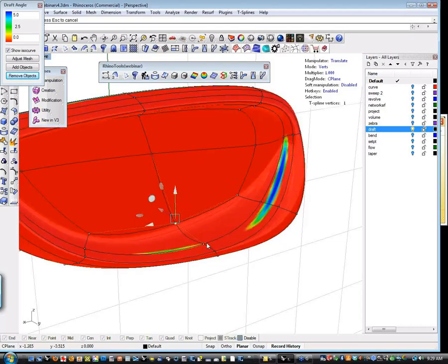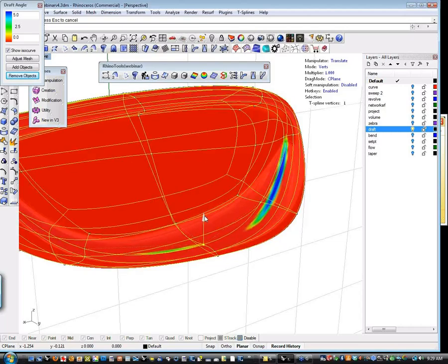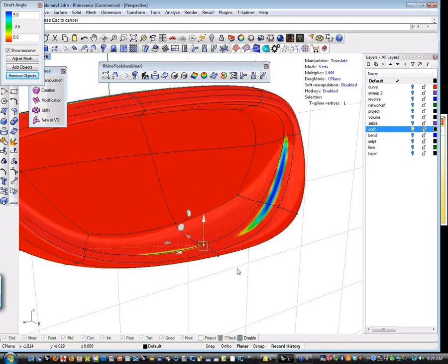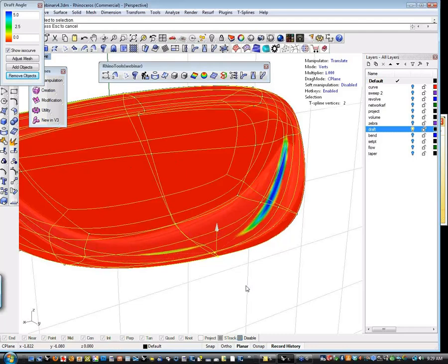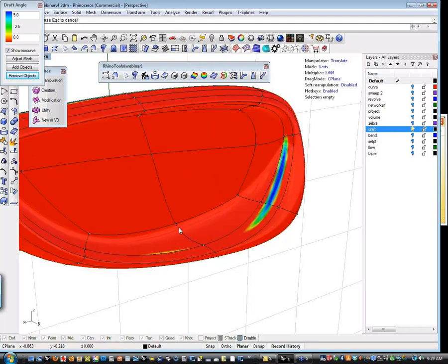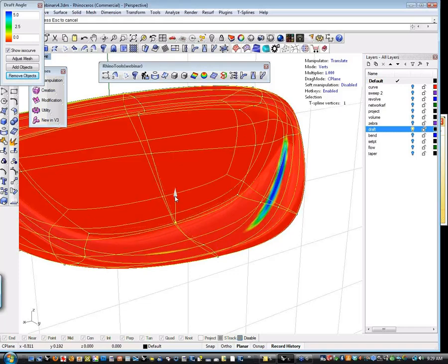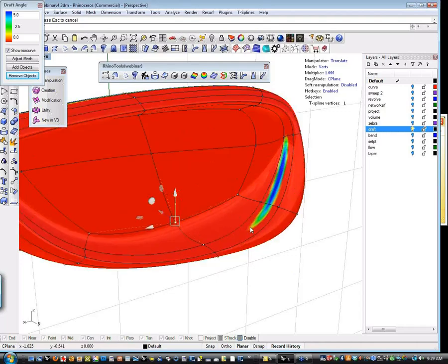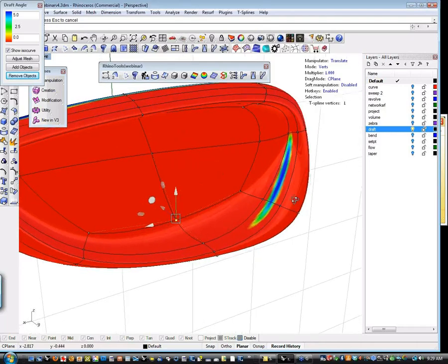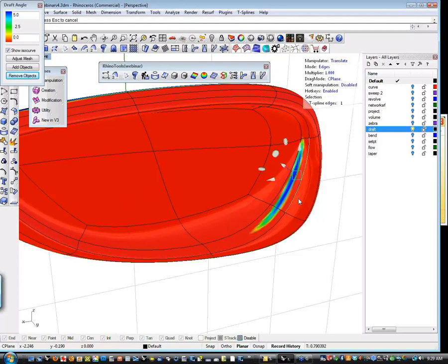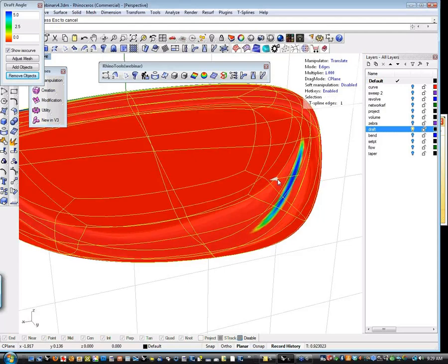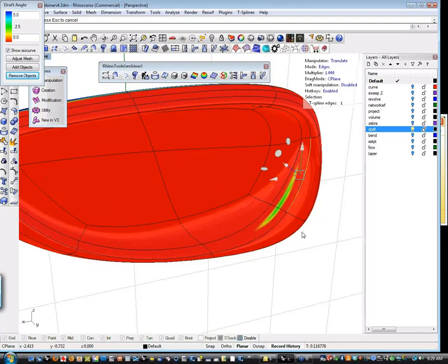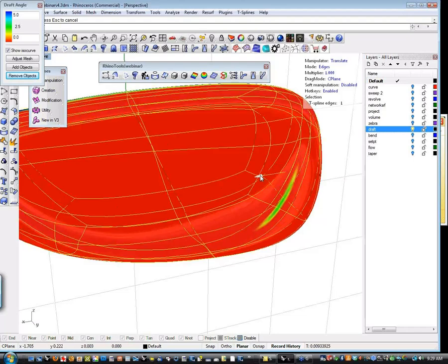disappears. And if you're looking for the one reason you came to this webinar, this is it right here, because being able to do this interactively and watch your undercuts disappear is nothing short of absolutely positively amazing. So I can just dial this in. My undercut's going to disappear. I notice I've still got another little undercut here, so I'm going to grab this edge and I'm going to just squeeze that out just a hair. I'm going to pull this one in just a hair.